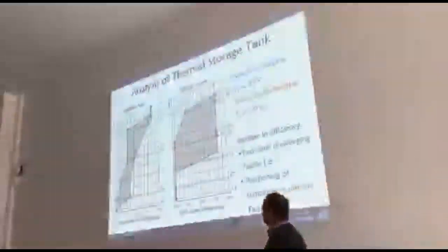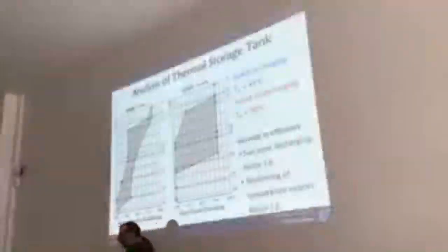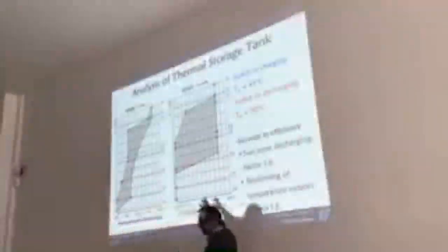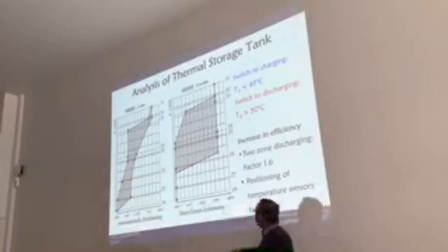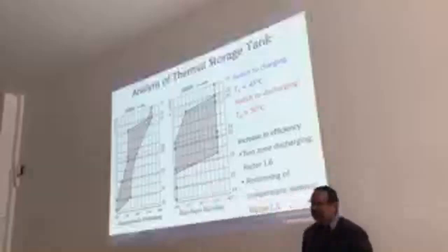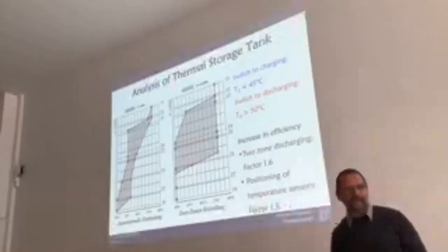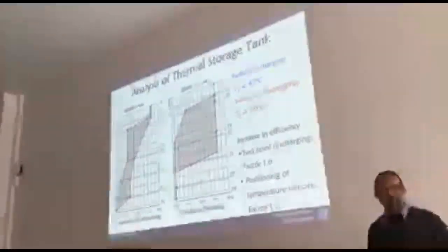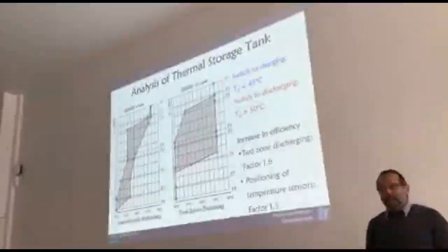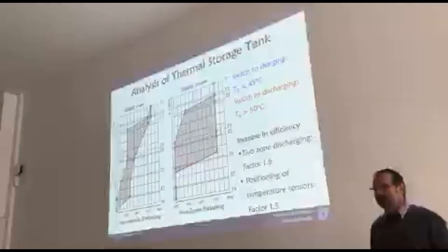So that was the storage capacity in the beginning. Then we changed the hydraulic system with these 4-way valves, and we got this solution. And you see the storage capacity was raised from 17 kilowatt hours to 27.4 kilowatt hours. That is a factor of 1.6. What would be your next idea to increase the storage capacity of that situation?